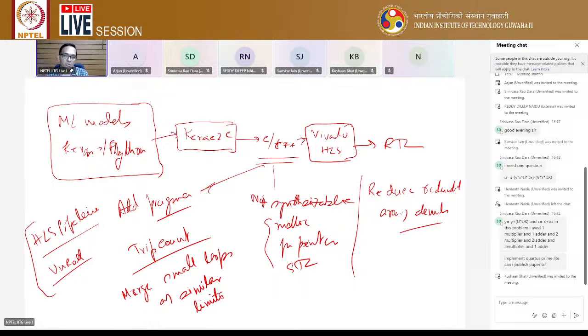If you keep such loops unnecessarily, your latency will grow. But if there are four such loops consecutively, you can merge them together. Now, each loop is 100 iterations, so there are four loops, which was 400 iterations earlier, 400 cycles, assuming one body of the loop can be executed in one cycle.